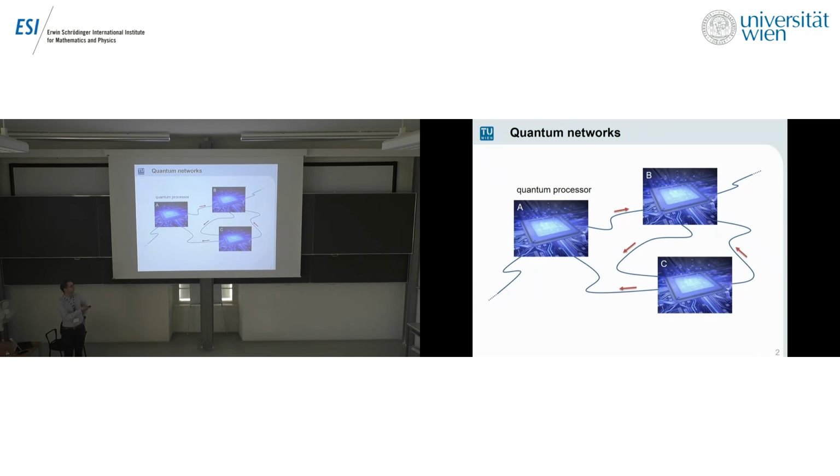And furthermore, if you then also want to send a signal from B to C, you also need some devices that make sure that your signal actually goes where you want it to go. For this, on the one hand, you need some kind of switches, and more importantly, you need some kind of non-reciprocal components. First of all, for example, isolators, which allow only unidirectional transmission of a signal, or circulators, which enable you to send the signal from one port to the next one, and so on.